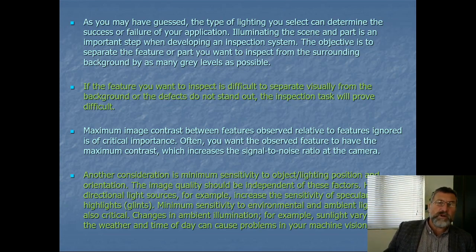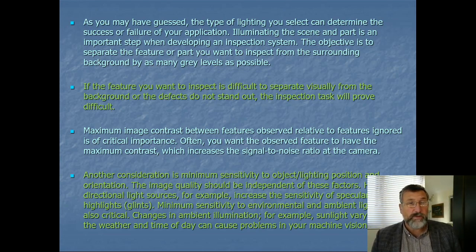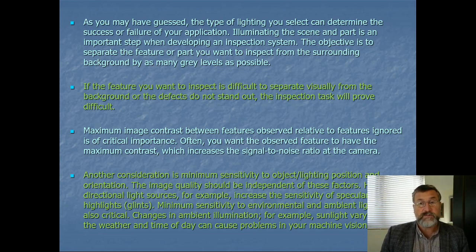One thing you can do to improve the signal to noise ratio is to use a laser of a particular wavelength and then match that to the transmission characteristics of a filter. We buy lots of filters off various companies. Then the signal to noise ratio will be increased dramatically, because a lot of the background radiation from various lights in the lab or wherever will be blacked out, because we're only looking for the wavelength the laser is at. So that's a technique definitely worth doing if you're using a laser.